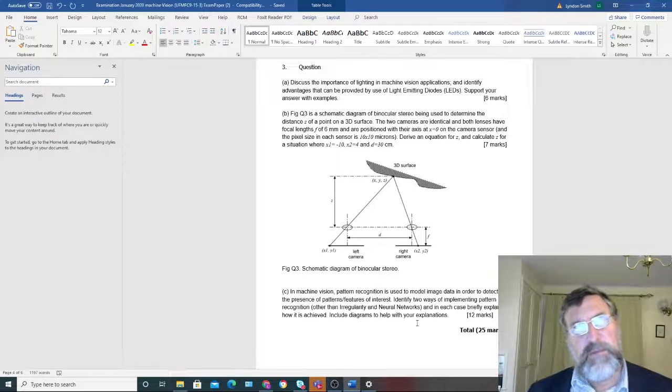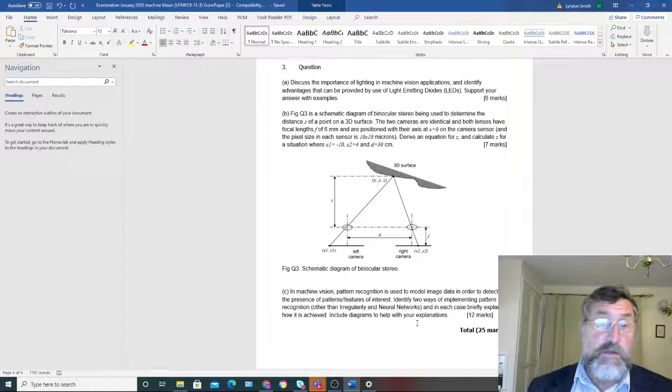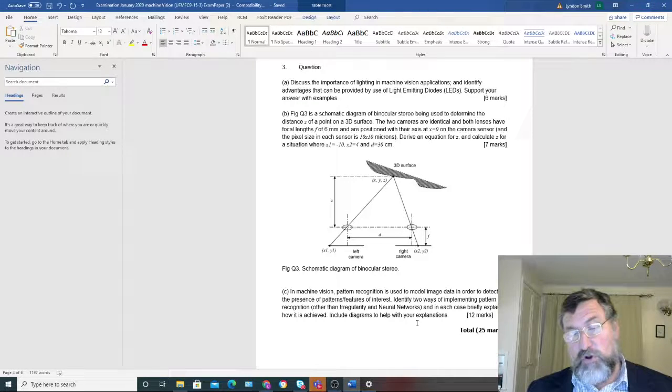Another example might be you might need an extended source. I talked a little bit about this when we were doing polished stone. We were polishing stone and looking for little defects on the surface, because any mechanical defects caused by damage to the polishing surface would not be acceptable in the stone. One way of doing that we found was to shine a light, actually using a fluorescent tube, and then use a technique called dark field illumination, or bright field illumination, whereby you look at the reflection.